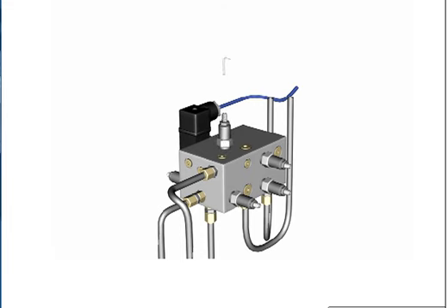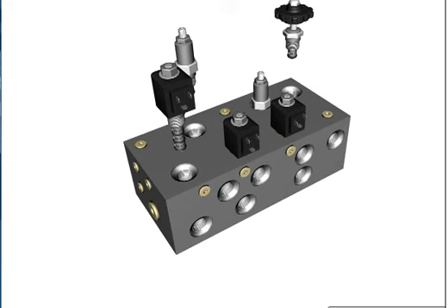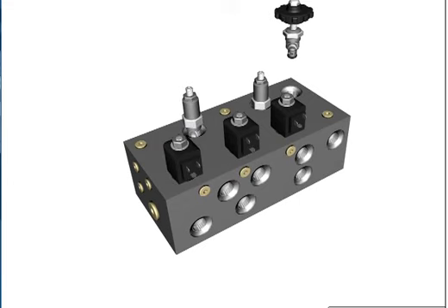Cartridge valves, used in combination with a manifold, can be used to create a common circuit free of potential leaks associated with external plumbing. Cartridge valves can be divided into 2 design categories, screw-in and slip-in. The screw-in style cartridge valve uses a threaded base to secure the valve in the cavity. Screw-in cartridges use either a spool, poppet, or ball valve element.